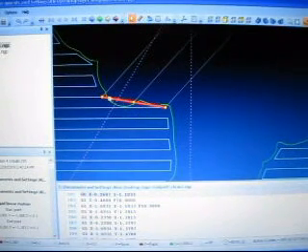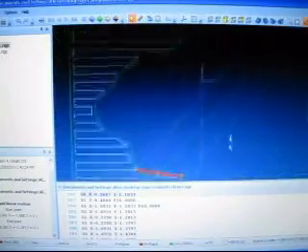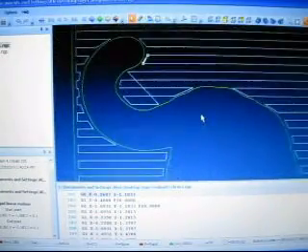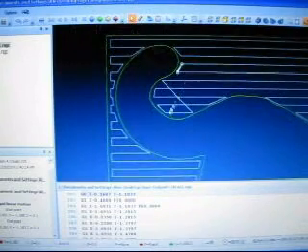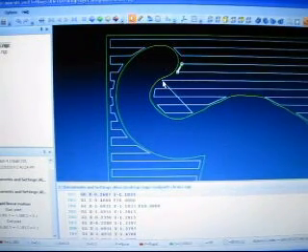Right there. Now let me just back up for just a minute. Remember we had a couple rapid motions that we took care of. Like here it was jumping up and then plunging down to here. Now this is fine. I eliminated the rapid, and we had a couple other problems here where it was rapiding to here, then coming back to here, and then rapiding over, and I didn't want all that.